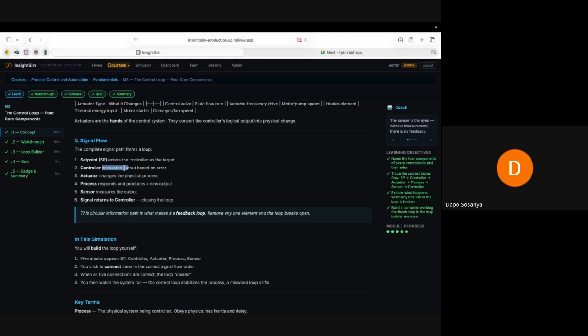The PLC is the hardware hosting the controller. Okay, don't let me confuse you. Let me not use controller. The PLC is the hardware hosting the algorithm that implements the control. So in this instance, we are talking about the PID algorithm, and it is the PID algorithm that does this calculation.